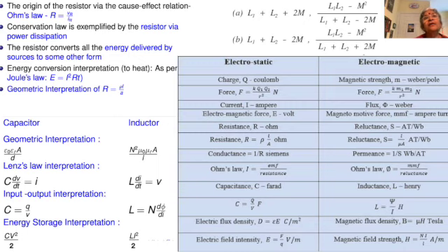So we have Ni by phi equal to R, a different kind of R written altogether differently, and it is similar to rho L by A, but with mu being permeability and not resistivity. It has a relationship as given by L by mu A. I suppose the rest follows through accordingly, so let's move to some of the applications with respect to problems.